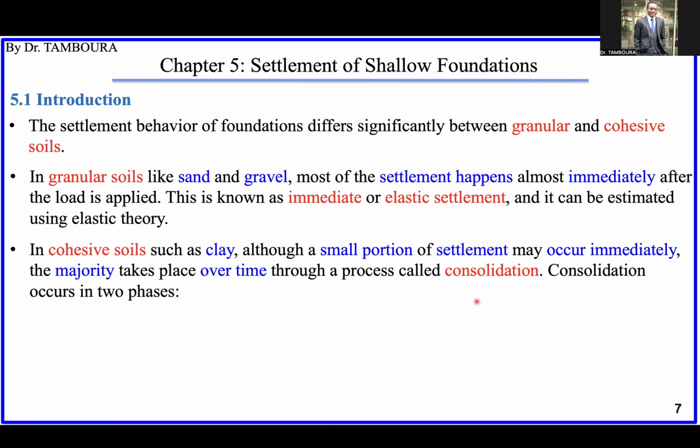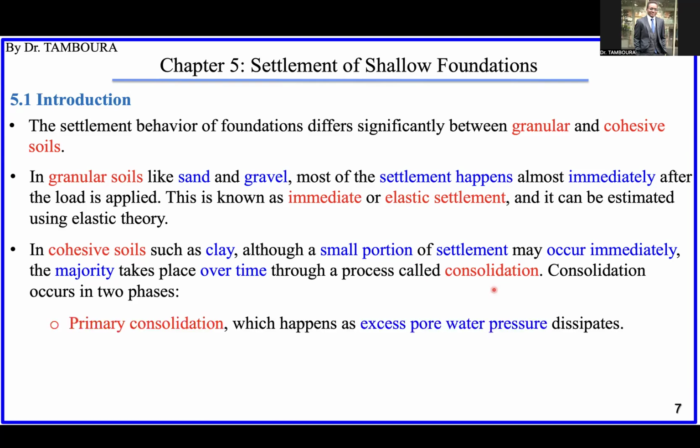This consolidation has two phases. The primary consolidation happens as the excess pore water pressure dissipates. It is related to how fast the water is going out from the clay soil. So the primary consolidation is related only to the water in the ground, the release of excess pore water pressure.